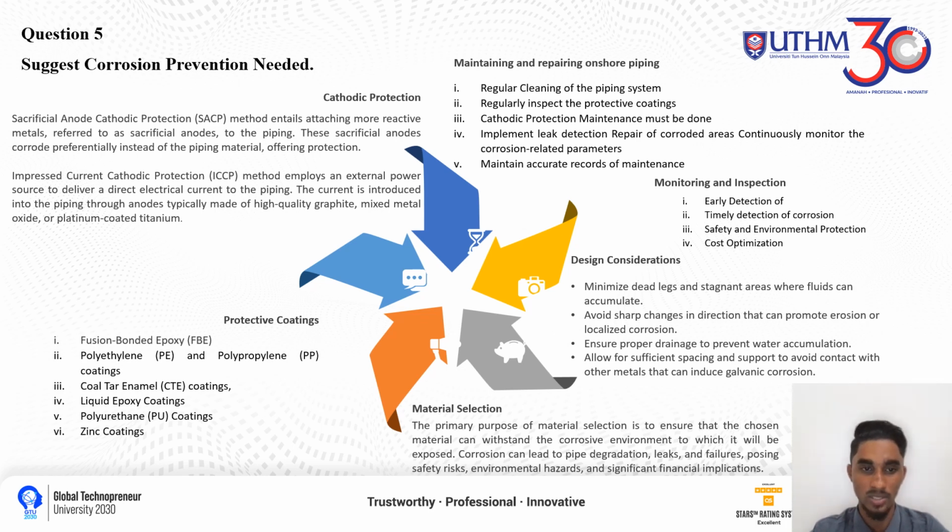and certain chemicals. Next is the liquid epoxy coatings, which encompass solvent-based or water-based epoxy formulations that are either spray applied or brush applied on the pipe surface. These coatings undergo curing to establish a tough and chemical-resistant film. They exhibit reliable adhesion, flexibility, and resistance to impact and abrasion.